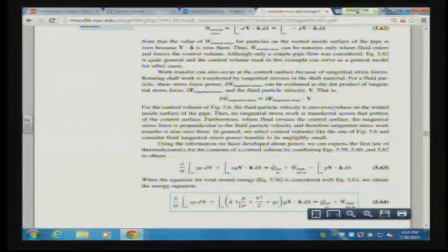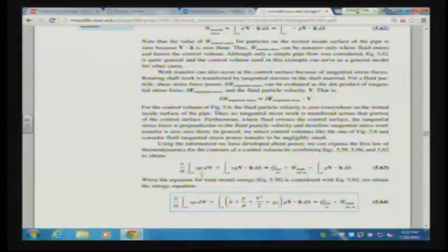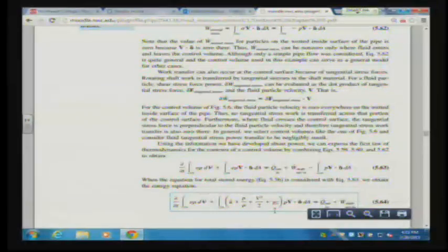These three terms are what we see in one form or another in the Bernoulli equation. Does that look familiar to you? Now we have added in this internal energy term because we have to take into account the state of the fluid in terms of its temperature, its pressure, and so forth. But really, we're coming up with something from this very mathematical material derivative, Reynolds transport theorem point of view that starts to look a lot like Bernoulli, which we came at from an entirely different angle.